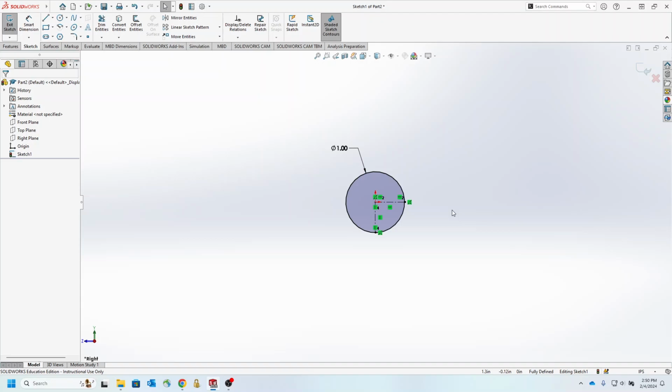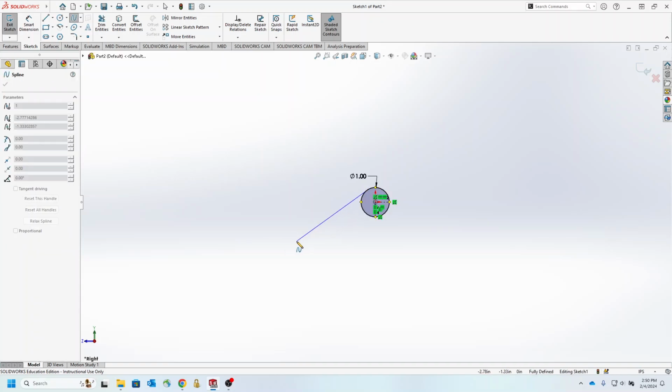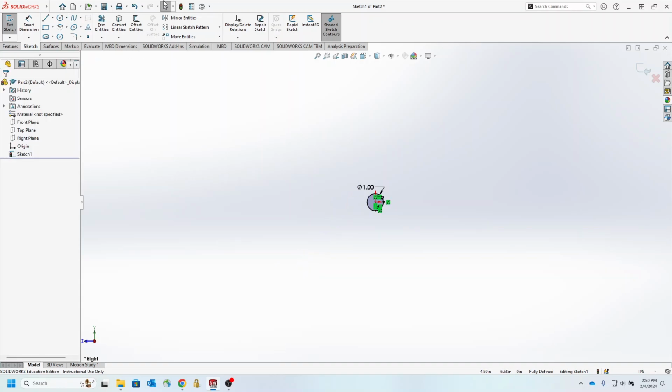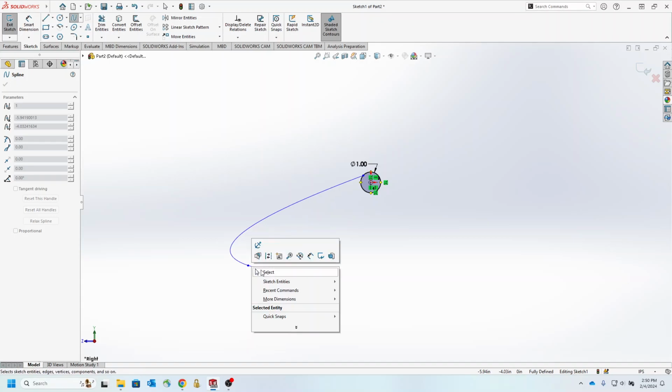Now I'm trying to create a side profile of that shoehorn, so let's use a spline. With a spline you can create a curve, and depending on how many points you add, the curve can be defined differently. This is 2 points. Let me start one more time. Select spline, and not on these two corners, select something here, this point, go all the way here, release the spline point, and right click, select.